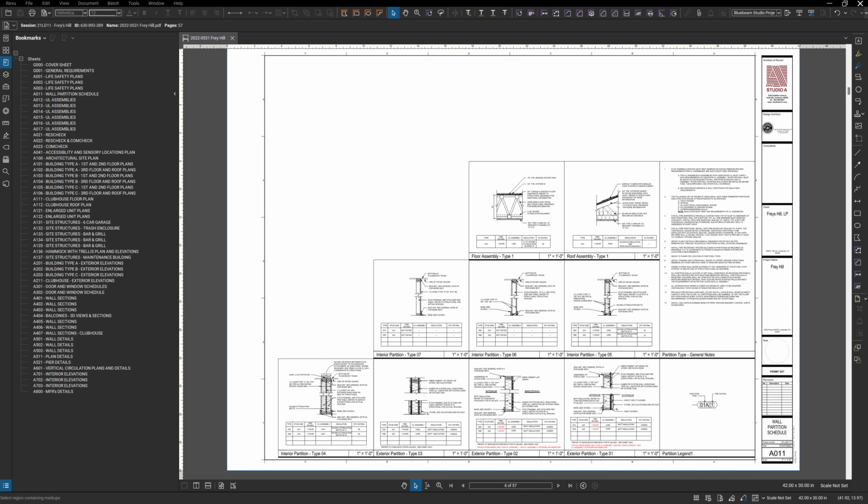So why do we have this sheet? Well, this sheet kind of covers us for a lot of assembly information, so we don't have to say it multiple times. For example, we do our exterior partitions and we kind of delineate interior breezeway versus just regular exterior. Again, the interior breezeway, exterior partition type 2, we have that pulled out as a separate piece for the same reasons we talked about earlier in the life safety sheets. Based on the jurisdiction, it could be assembled differently and have a different fire rating requirement.